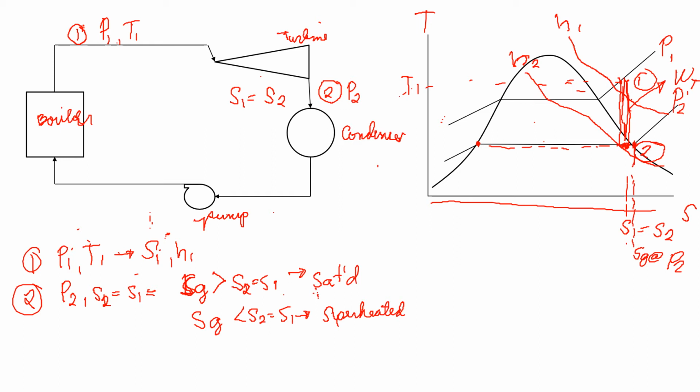Heated. And you have to interpolate. But if you find your SG greater than S2, which is equal to your S1, and you found it saturated, okay, you have to say S2, which is equal to your S1, is equal to SF at pressure 2